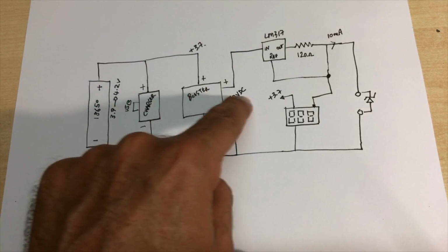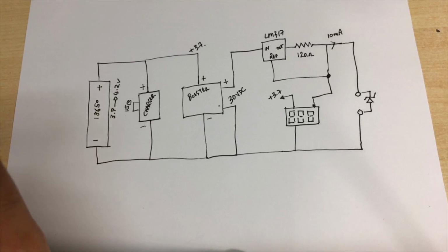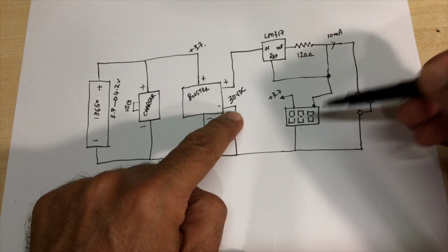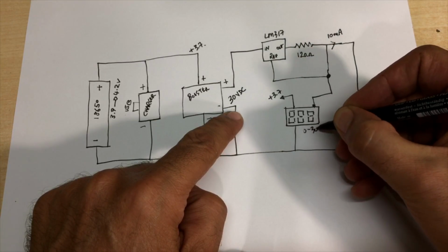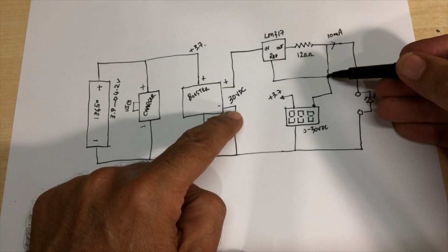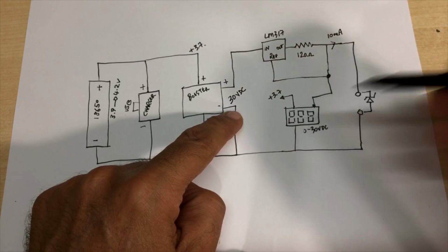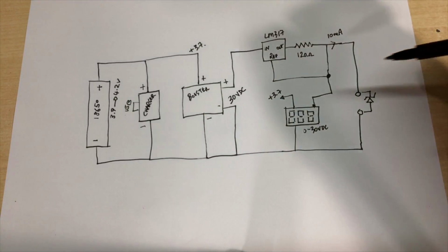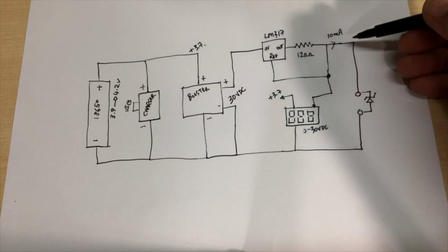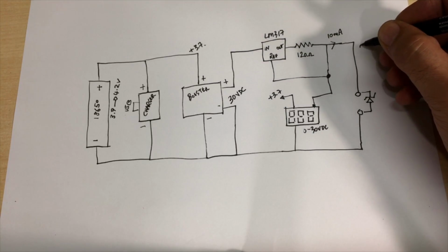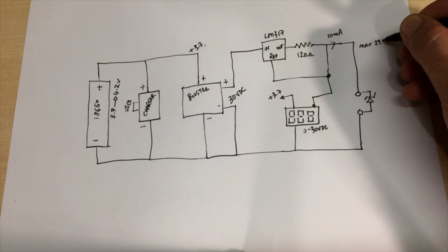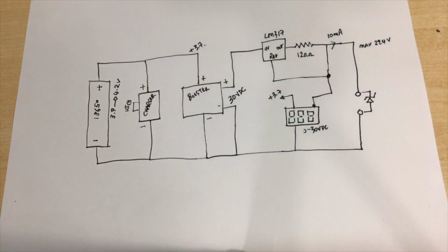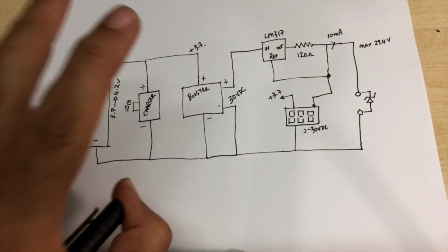The booster can go up to, I believe, about 40 volts, but I'm putting up to 30 for the simple reason that my meter here can measure 0 to 30. I don't want more than 30 volts at this point, otherwise I exceed the limits of the meter. And that's the meter module that I have. So if I put in 30 volts there, I get about 29.4 volts. I can measure Zener diodes up to 29.4. And that's what I'm going to build now.